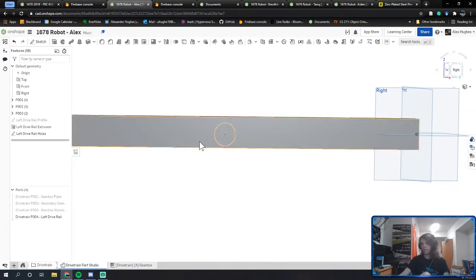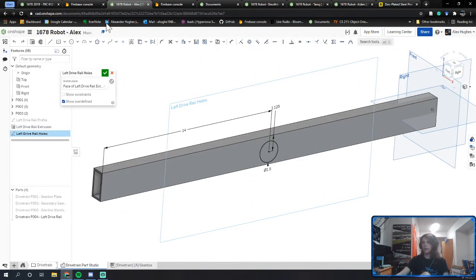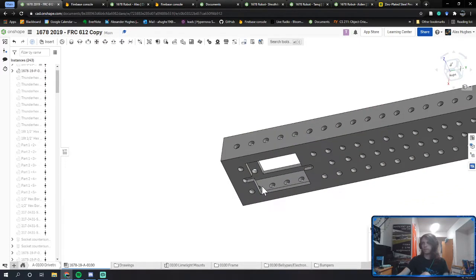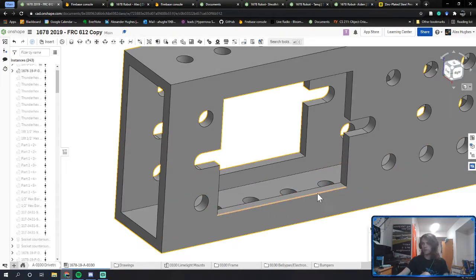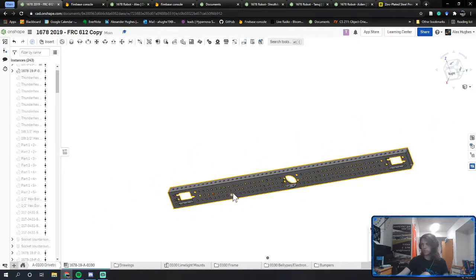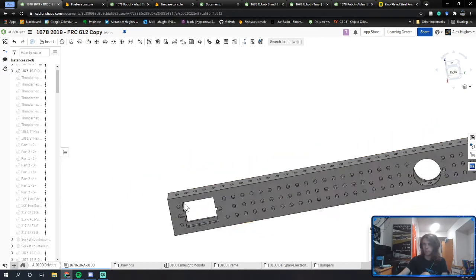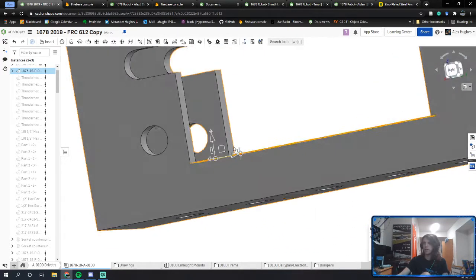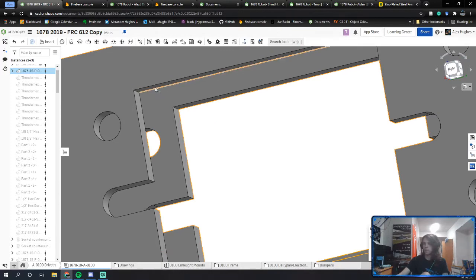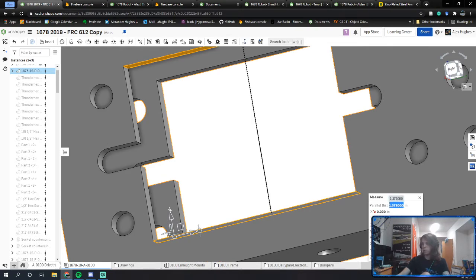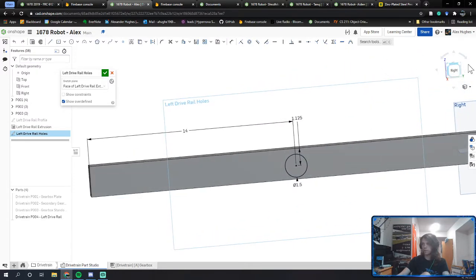Cool. So hopefully you all are following along. We're just going to continue down the line and look at some of the other stuff they have here. So they have a rectangle, and the rectangles are at each end. I'm going to model this left rectangle first because I don't know if they are identical. I think they are. We will verify that later. So this rectangle is, first off, 1.378 inches high. I'm going to go ahead and actually start modeling this.